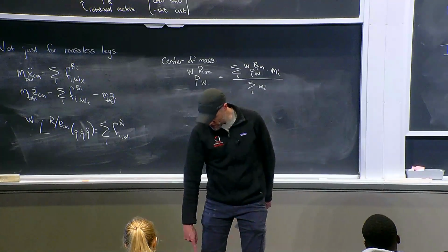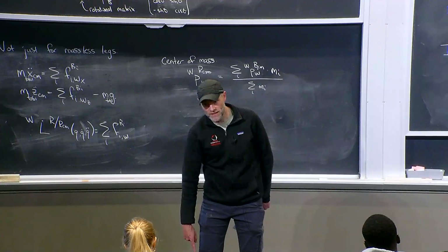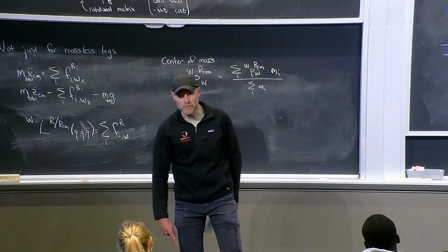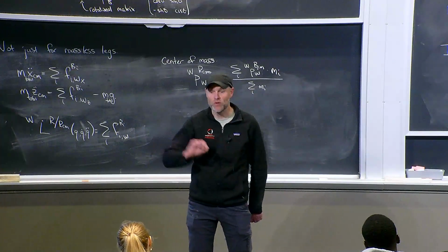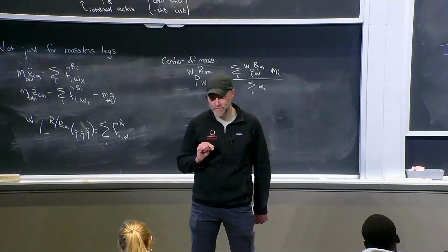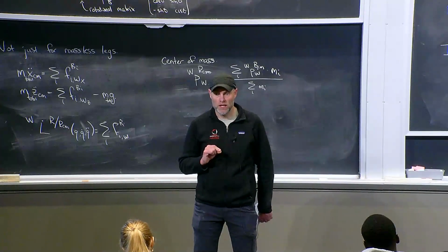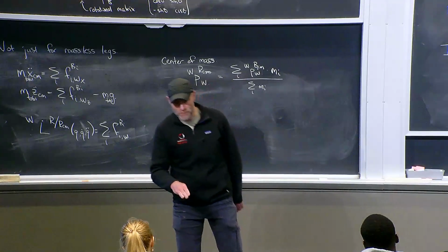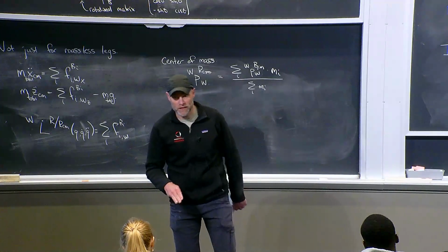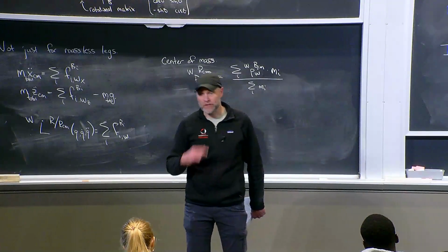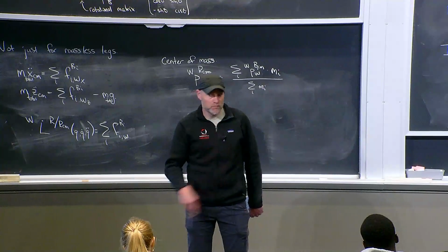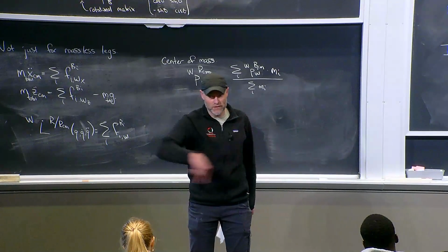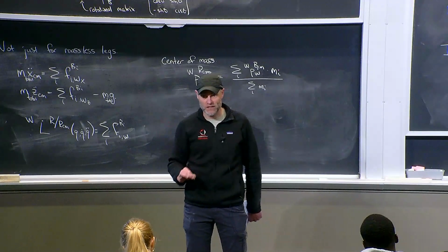But if your center of pressure is nicely on the other foot, then you can pick that foot up smoothly, and you don't have a discontinuity in center of pressure. It does require, in order to achieve that, that you pick your foot up slowly. You won't just immediately pick it up. But it's possible to execute that trajectory once you have a trajectory that's safely inside the support polygon.